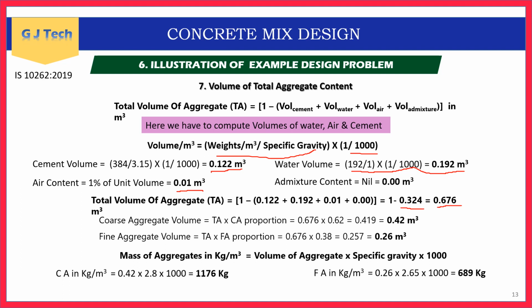In some particular cases, the code also specifies the minimum water content required, so we can also check. Usually it will be higher, but for special concretes sometimes this also has to be checked against the minimum water content required. So here we are not doing that.